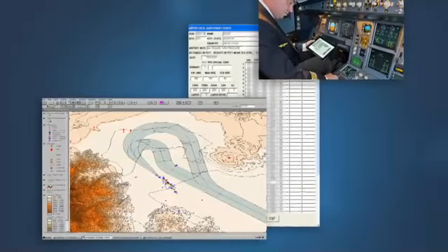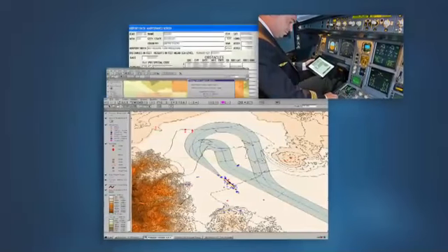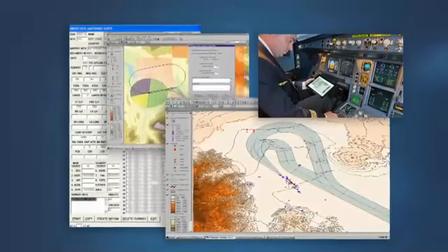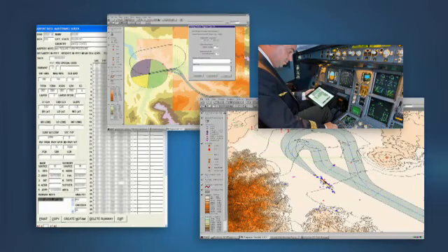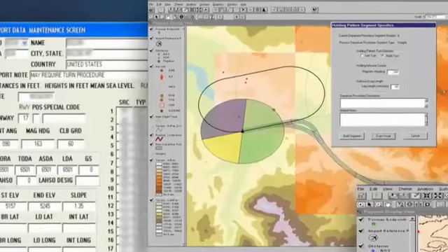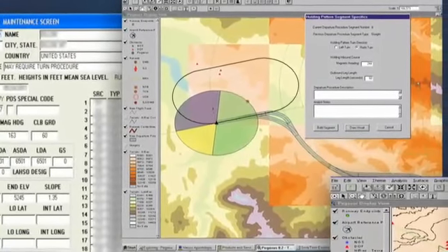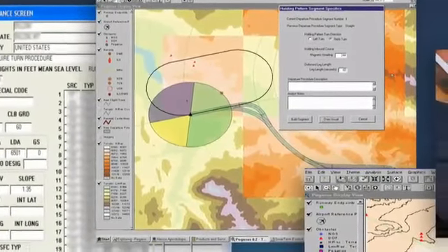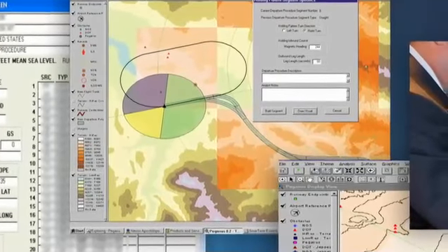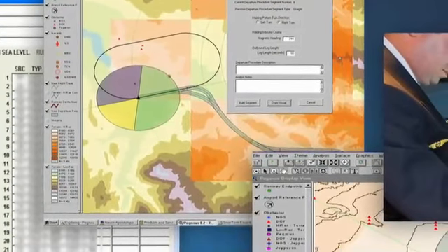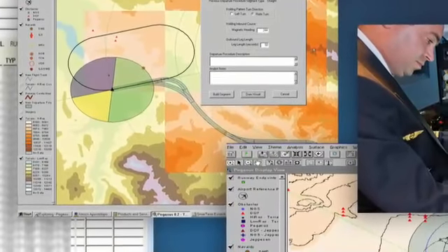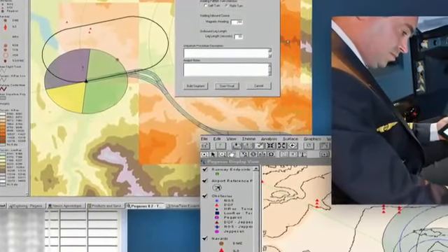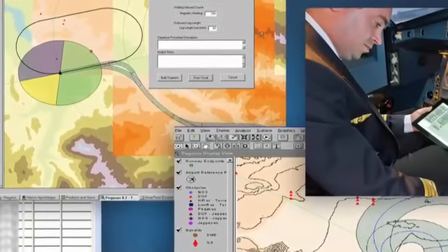Rather, it is expected that the analysis is completed by a professional aircraft performance engineer or a performance engineering provider, with the necessary training and resources available to make full use of data provided in the airplane flight manual. In addition, they are expected to collect and maintain an obstacle database using the best and most current data sources available for use in performing the analysis. In many cases, electronic performance data is now being provided by manufacturers, and in some cases, the flight manual performance data is no longer provided in paper form.